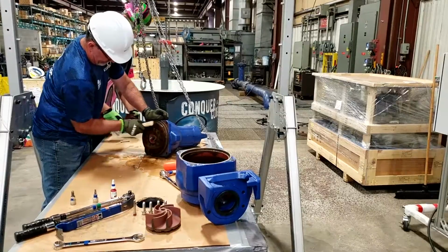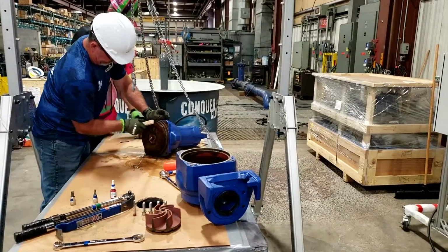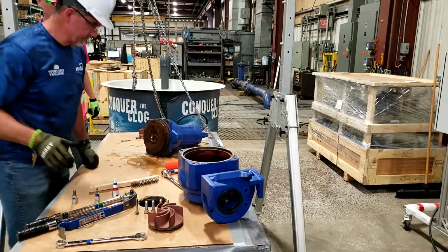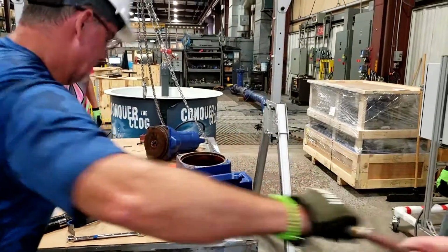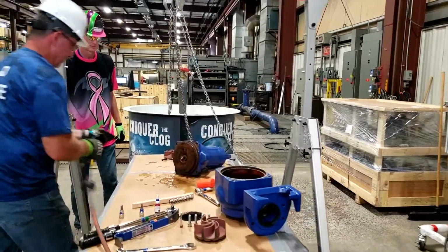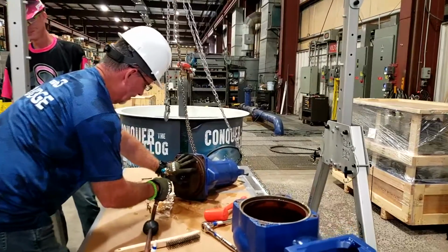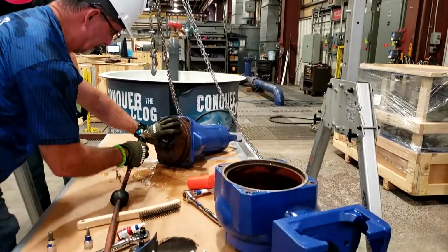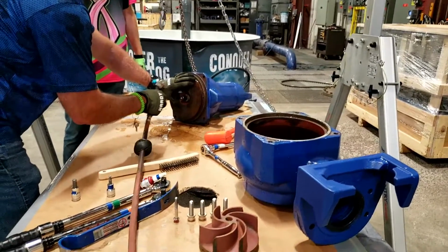Clean the intermediate casing wear plate using the wire brush by making 3 passes in a circular motion around the wear plate. Using the air gun, blast air into the impeller bolt hole on the shaft for a count of 5 seconds and verbalize the count: 1 1000, 2 1000, 3 1000, 4 1000, 5 1000.